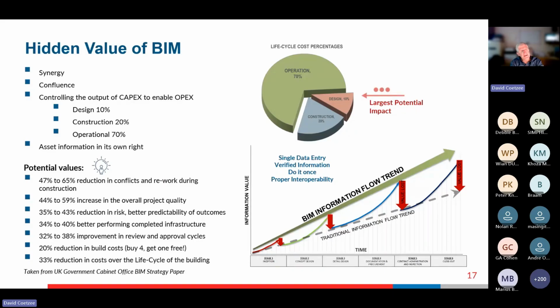So in a simplistic view, the software will tell you that's a clash. You can exclude that, but the problem is we federate each week, so we don't exclude it, we just ignore it. And sometimes clients who don't understand it get very excited when they see the dark red and literally thousands of clashes shown there.